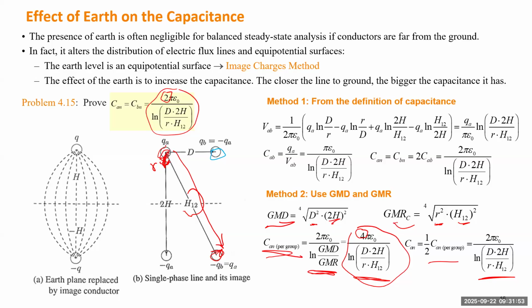So such a restoration plan is very different from a system with all overhead lines. With overhead lines, if you energize a long transmission line, when you increase the load, it may cause a low voltage problem. But for the Long Island system, the overvoltage problem can be the main concern.